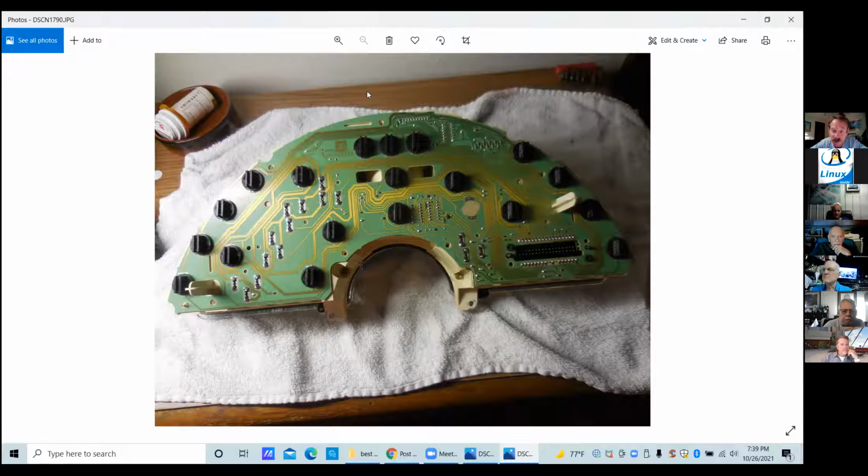He says those connectors go bad. So I used my brand new solder extraction tool that I bought to fix the ham radio that we all talked about a couple of months ago. I removed all the solder, and then added new solder, as he said. I soldered that up, checked all the bulbs, found one bad bulb, bought some new bulbs, and put one bulb in.